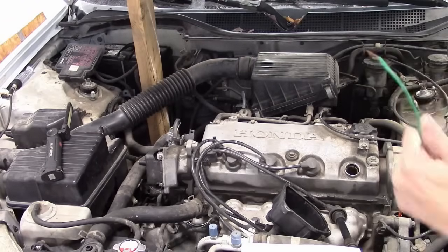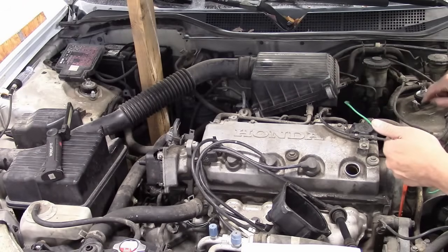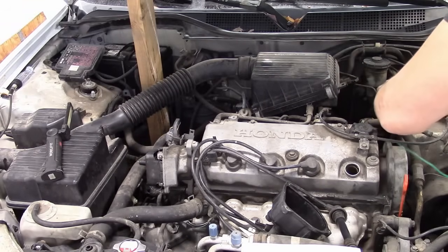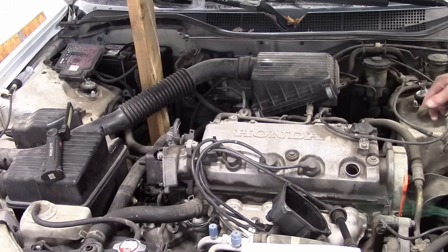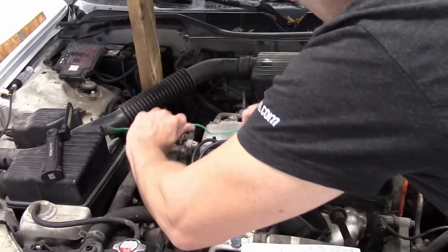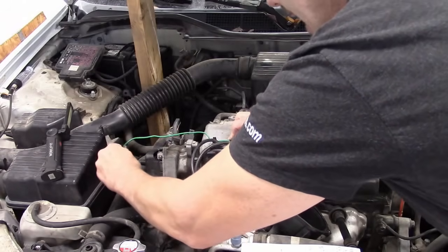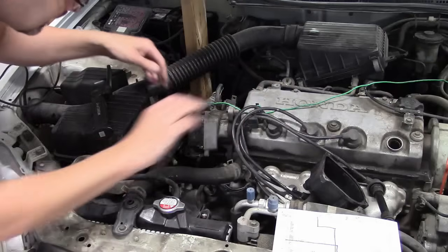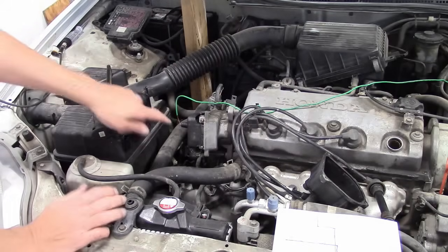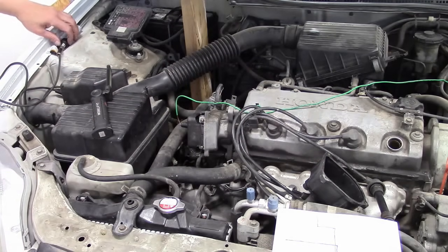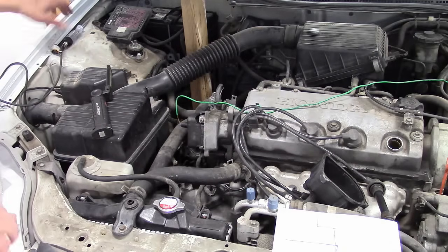All right, so I've got some wire here. What I'm going to do is put this wire to a ground here. Make sure that's on there really good. And I'm going to make sort of a spark plug in a way. So I'm going to run this along and then have this gap right to the coil output. Yeah, like that. So if I do produce a spark, I should be able to see it jump to the wire, and it'll just go to a chassis ground there on the shock tower.